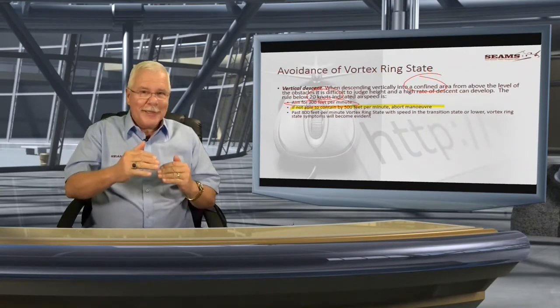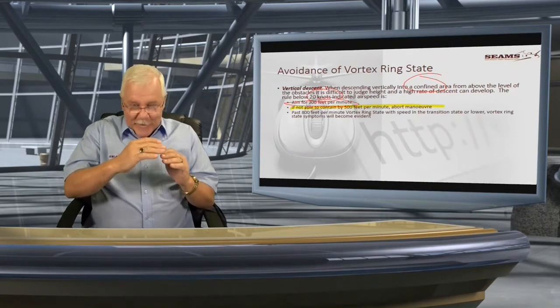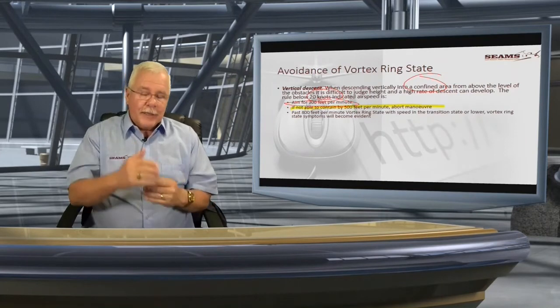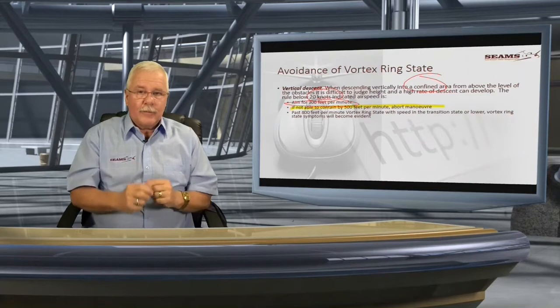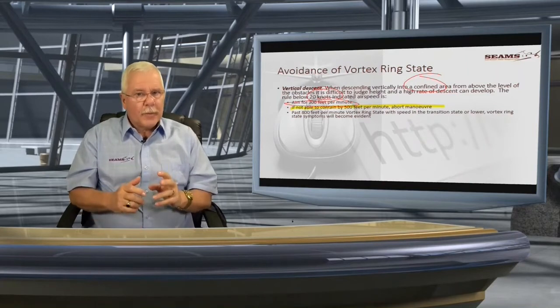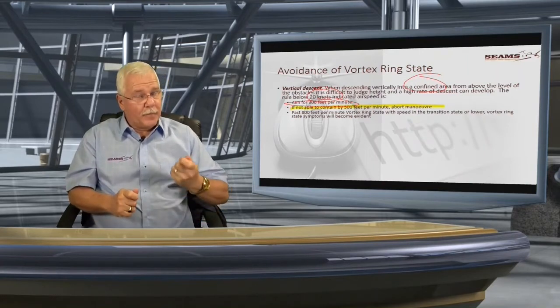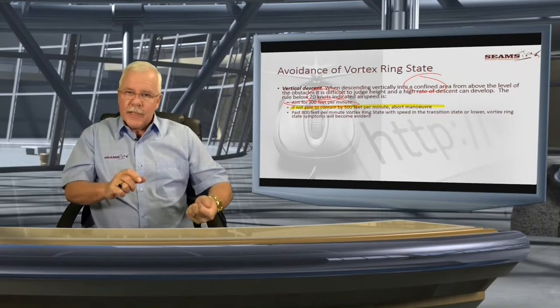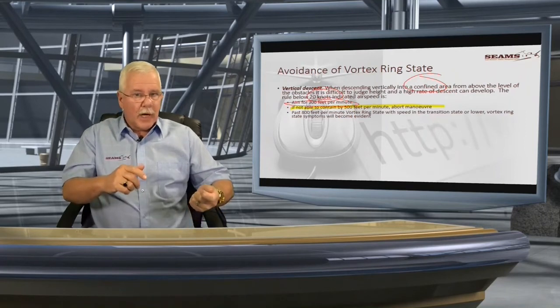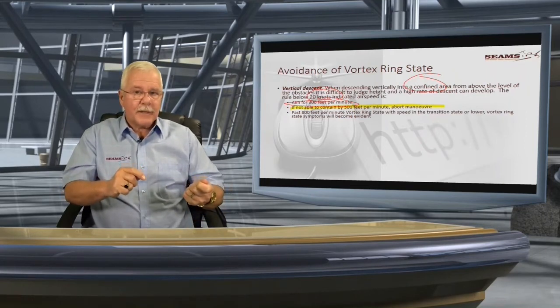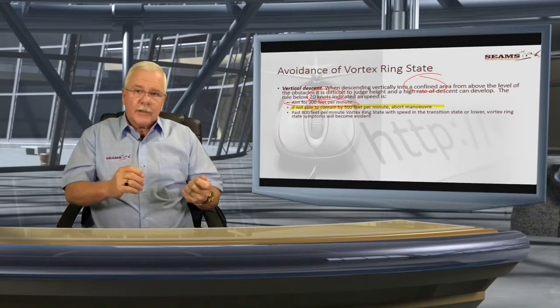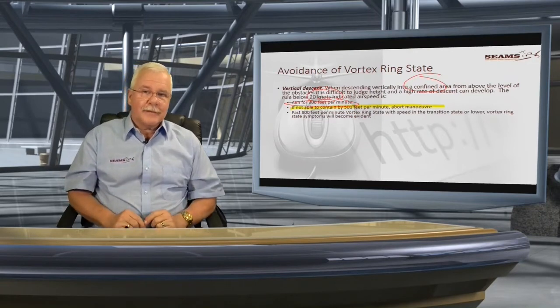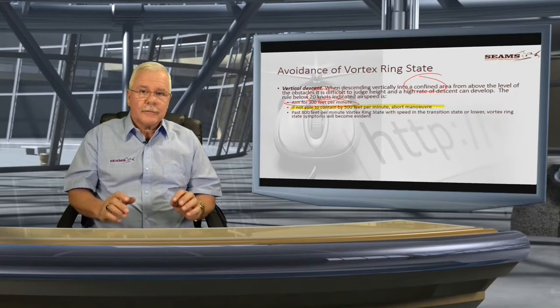So between, we say 300 feet is what we're aiming for. You get up to 500 feet, you'll probably be okay. But if you find that coming up to 500, you're testing, and you see, whoa, I can't arrest the rate of descent. I can't control it to a lesser rate. Break off. How do you break off?